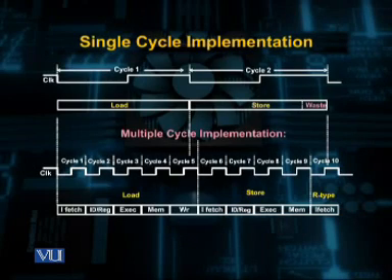Similarly, in the case of the load instruction, the instruction is completed in the first 4 microseconds, and the system remains waiting for the tick of the clock for 1 microsecond, and in this way, this time goes wasted. So, if we look into this whole scenario, we can say that the multi-cycle data path is faster. In this example program, it is faster by 1.24 times, that is 24% faster as compared to the single cycle data path.